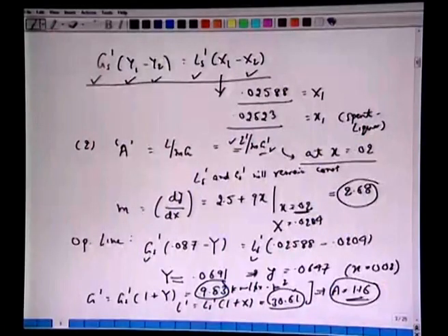So, we have to do this calculation: we have to find out what is Y corresponding to small x. For that we wrote down the operating line equation, which connects the bulk phase concentration, given x, what is Y, knowing the flow rates. From there we get a small y, we calculate the capital Y, solid-free basis, and then we calculate L prime and G prime at that location where we have this mole fraction equal to 0.02. The slope of the curve, we know the equilibrium curve, we differentiate to get dy by dx, and we substitute this number for a small mole fraction. So, this part we have done without graphically.